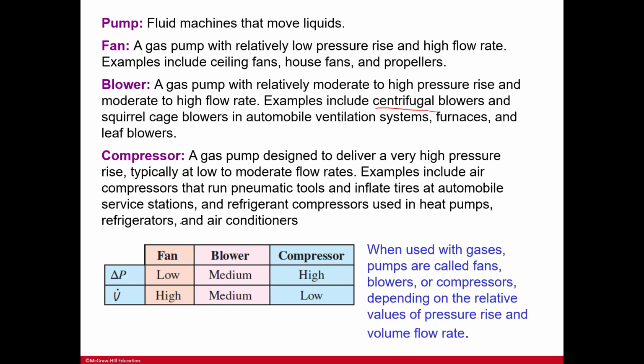And so here is just a diagram. If you have a change in pressure that is low, that could be a fan, medium could be a blower, high could be a compressor. And then if you have a volume rate here, if you have a high volume rate, you've got a fan, medium volume rate, you've got a blower, and low volume rate, you've got a compressor. When we use them with gases, pumps are called fans, blowers, or compressors, depending on the relative values of pressure rise and volume flow rate.